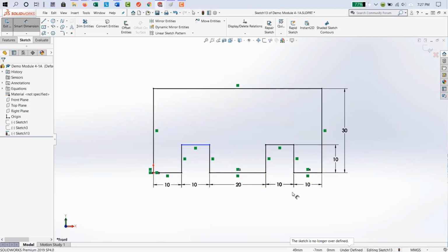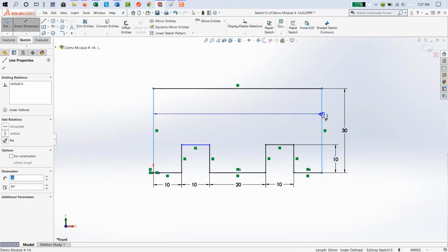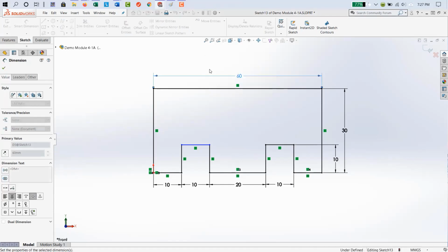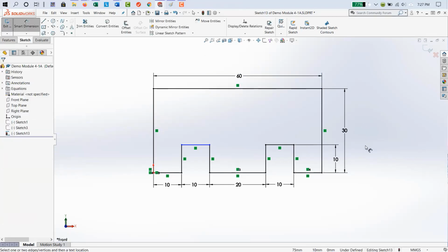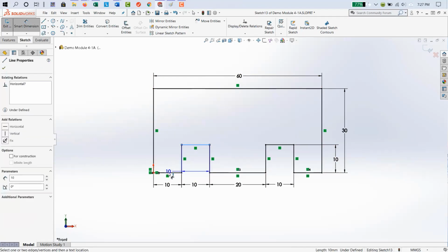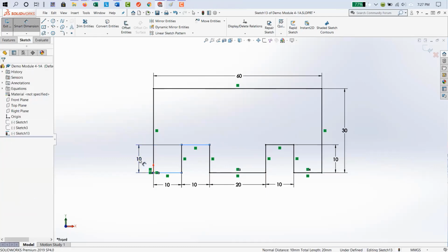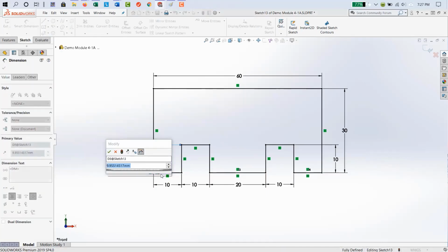All right, so to fix that error, what we want to do is delete one of the dimensions from below. Very simple fix. Then we reset the dimension above. And yes, you do have to delete or cancel and reset the dimensions, otherwise it will be a different color and may give you an error in the future. So we want to make sure that those are the same. Now we have one more dimension here. There we go, and that should be 10.